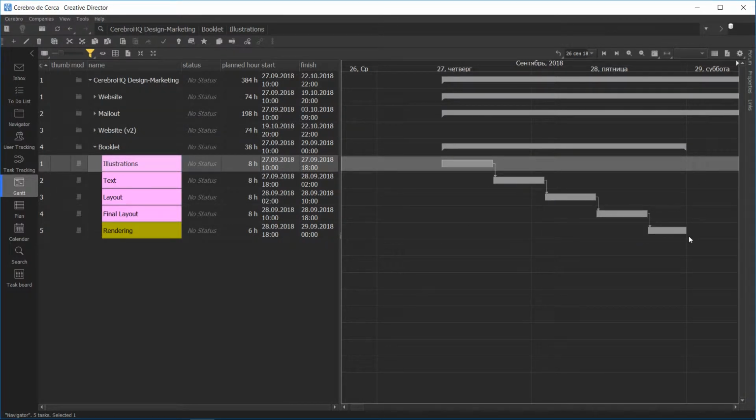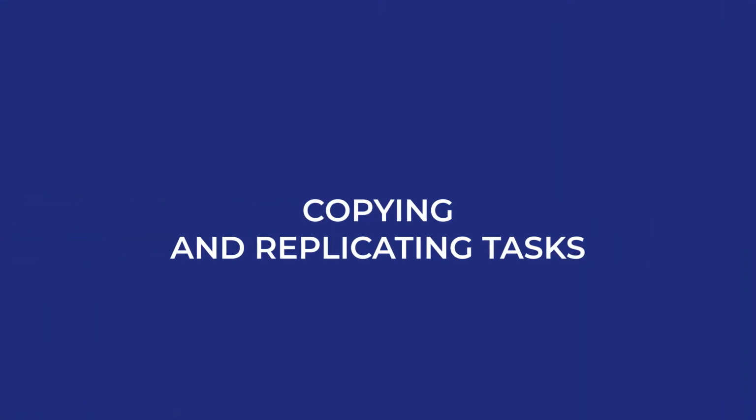You can manually edit links between tasks if you need to set up more complex dependency relations. To unlink, right-click on the task line, and when the menu pops up, choose the command to break one of the links. To create a new link, drag the circle marker on a task line towards another task. This will result in an automatic recalculation of a start time for all the tasks that depend on this predecessor.